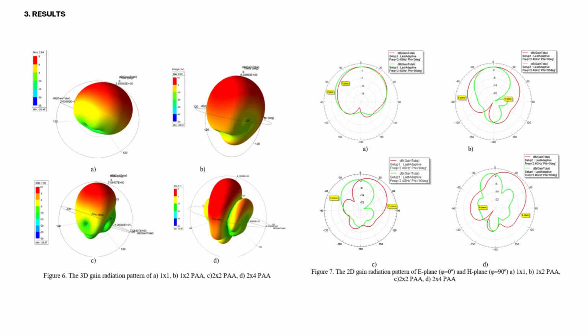From the given three-dimensional radiation pattern in Figure 6b, it can be seen that even in the back lobe there is a certain level of radiation intensity. Furthermore, the gain has increased to 7.08 dB for the four-element patch antenna array, and to 9.70 dB for the 8-element patch antenna array. It is shown in Figure 5, C and D.